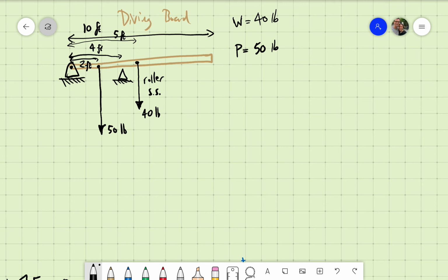What else? Okay. Third thing to show on a free body diagram is the normal forces or the reaction forces. Now in this case, we will have three reaction forces. A pin has 2. A pin, I hope you can see that's an arrow, has the, let's call this R1Y. Okay, it's at like location 1 vertically, so hence R subscript 1Y. A pin joint also can resist horizontally, so we show R1X.